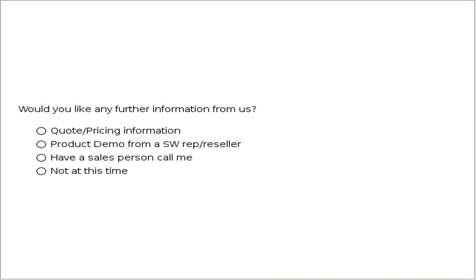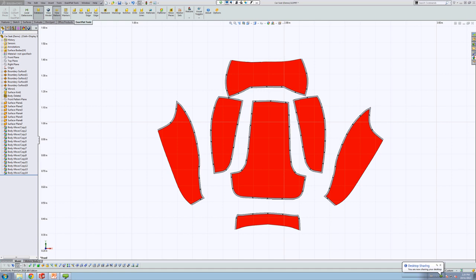There were a lot of questions about materials. What kind of materials can you handle? Well, we have a number of algorithms that support anisotropic, isotropic, and orthotropic materials as well. If you're talking about what kind of materials we can handle from a flattening process, the programs and the algorithms were designed for flexible materials. And we do have companies using it for complex metal forming, like for ship hulls and things like that. But any range of materials that you have the engineering characteristics for, we do support.